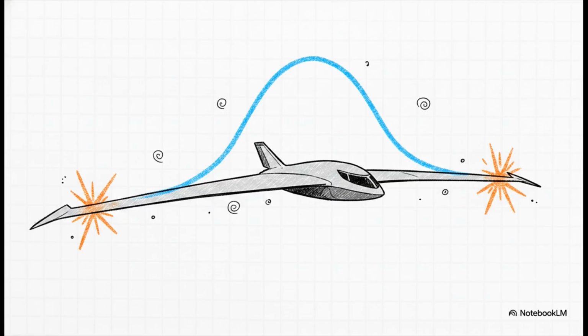Well, expanding on some brilliant research by German engineer Ludwig Prandtl way back in 1933, a team at NASA Armstrong designed and validated a wing that uses a completely alternative bell-shaped span load. Rather than fighting physics with drag-inducing ailerons or big rudders, this sharply tapered wing uses twist to achieve a bell span load. And, incredibly, this actually produces induced thrust at the wingtips when you use the ailerons to roll.